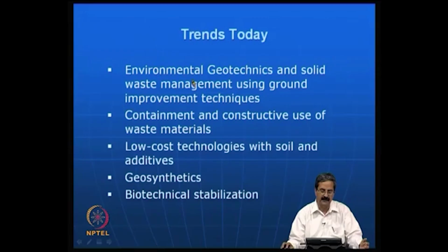So, what we do is that we take what we call municipal solid waste, and we try to understand the behavior of municipal solid waste and leachate compositions and their effect on buildings and foundations. If you have a leachate of very high concentration and it affects the concrete and steel when you construct a foundation, it is going to be risky. So, you do not want that. The knowledge of environmental geotechnics is required, particularly in understanding compressibility, shear strength and permeability, some of the engineering properties, and also the quantity and quality of leachate, its long term and short term effects.